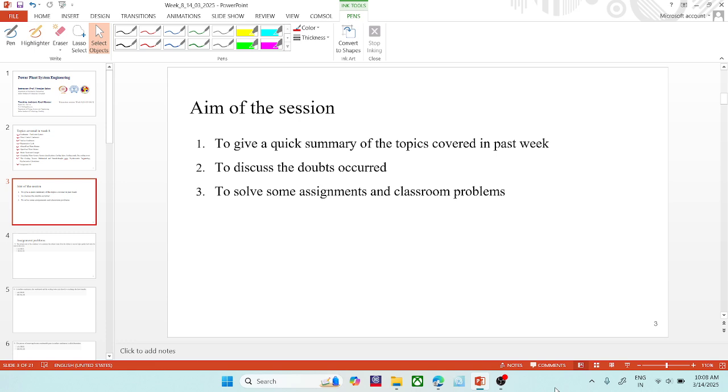So if the non-condensable gases are in the system, then the condensing pressure can increase. The second effect is they blanket the heat transfer surfaces, resulting in a severe decrease in the condensing heat transfer coefficient, so they can also decrease the overall heat transfer.